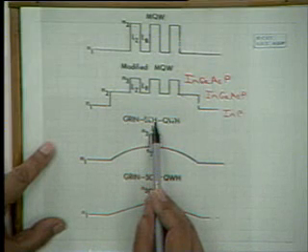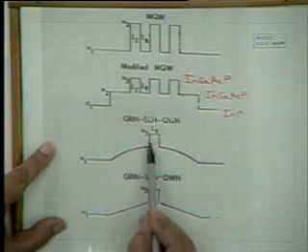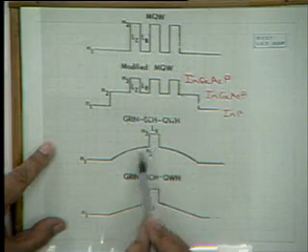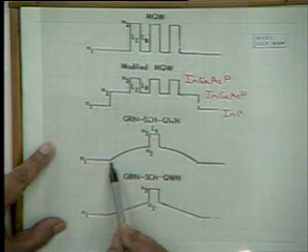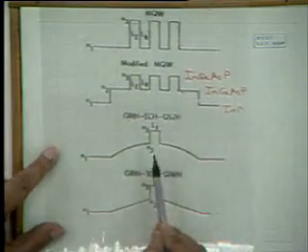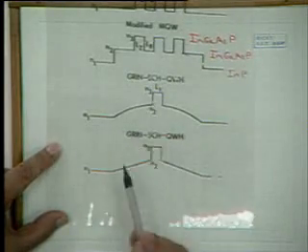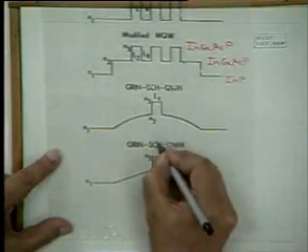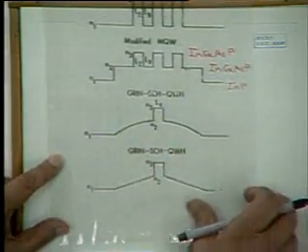separate confinement heterostructures. So with separate confinement, the electrons are confined here, and the light is confined here. This is the separate confinement quantum well heterostructure device. And here, instead of a parabolic, you can have a linear profile. So these are the basic types of structures that go into quantum wells.